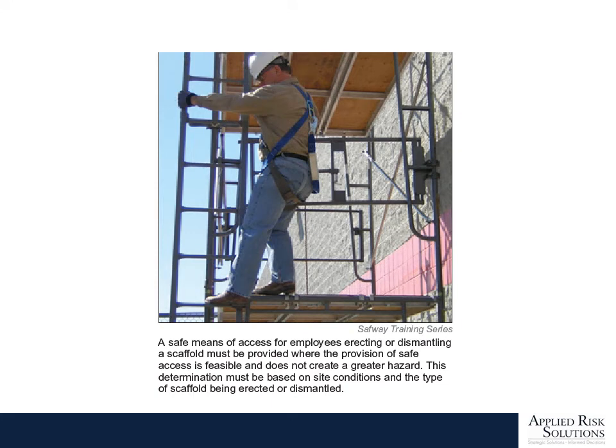Remember, when your people are erecting or dismantling scaffolds, they must use personal fall protection. Looking at this right here, I can't tell, but it does not appear to me that he is tied in anywhere. He's got on a harness, but what's he tied into?